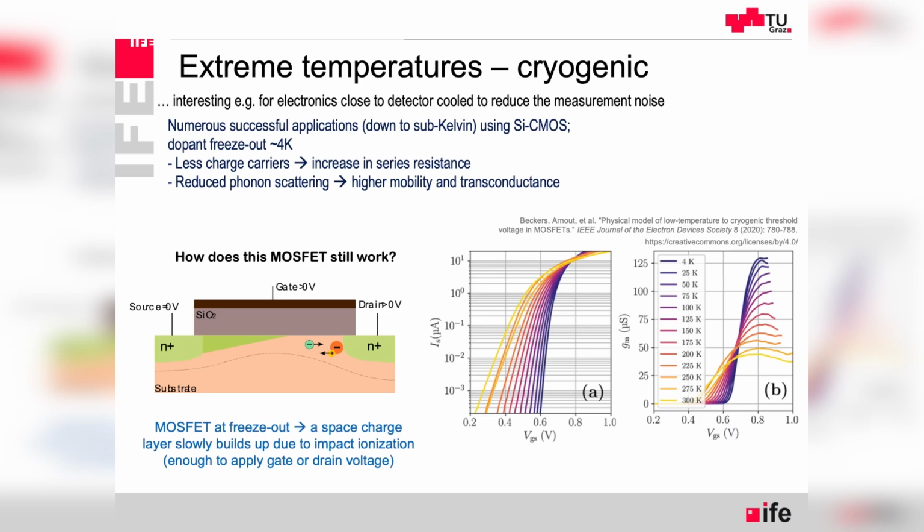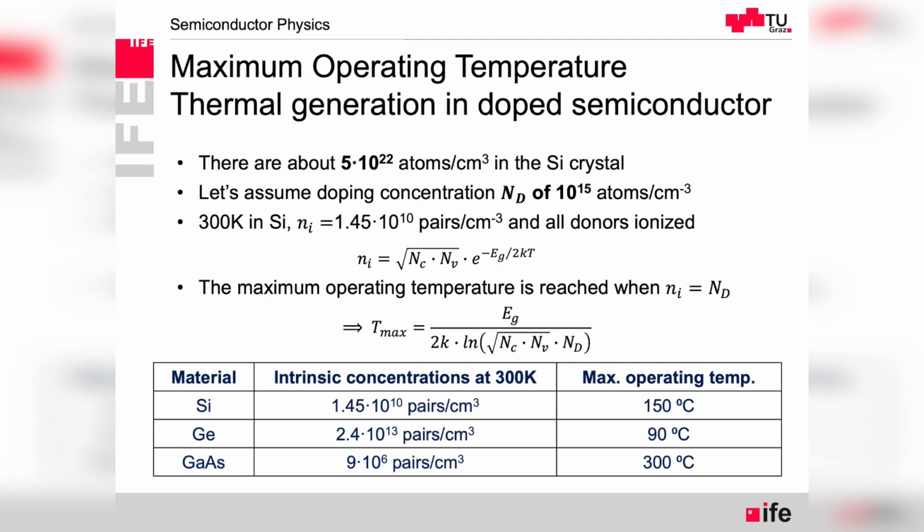It will interact with other atoms, and just by the impact of the moving charge carrier, it will give energy to another atom to ionize it. Because of this effect, we have charge carriers available for conduction without thermal energy, but through electric energy and charge carrier movement.